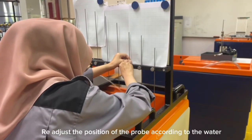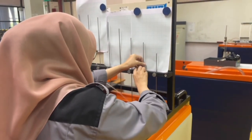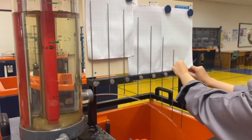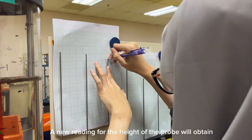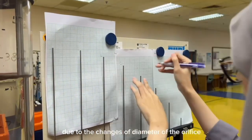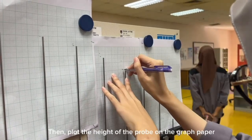Readjust the position of the probe according to the water flowing out. A new reading for the height of the probe will be obtained due to the change of diameter of the orifice. Then, plot the height of the probe on the graph paper for all readings.